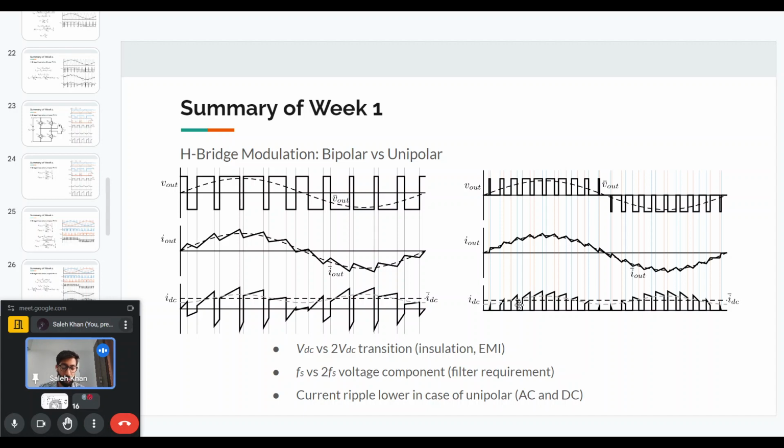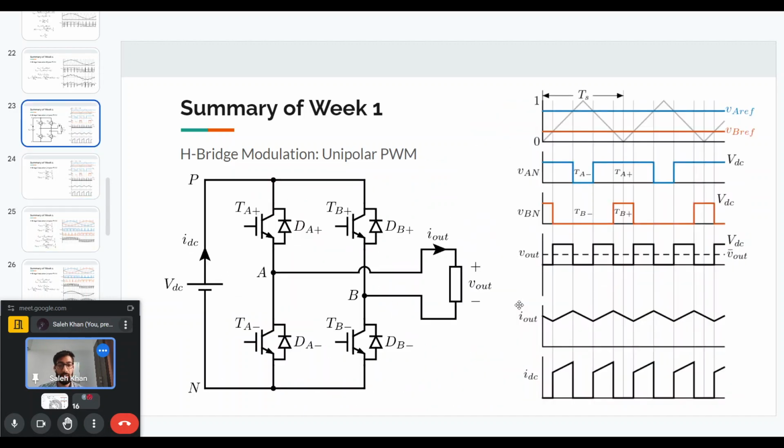What is usually done in these converters is we will have an input capacitor. In parallel with the DC supply, we will have a capacitor which is connected very close to the switches. This capacitor is supposed to provide the high frequency ripple, and we can also have other large capacitors to supply the low frequency, the fundamental second harmonic ripple. The idea is to have these capacitors filter out the AC component of the current, and